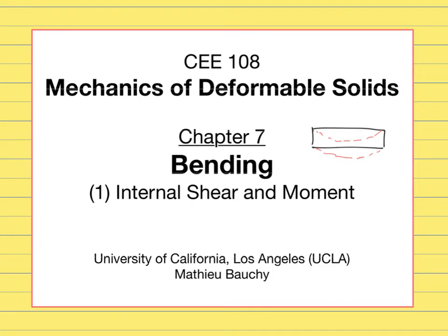So when you think about bending deformation, there are really two ways that you can induce a bending deformation in a beam. The first way is to apply a transverse load. So if you have a beam like this, and for example, you apply a 3-point bending like this, so you have two shear loads like this, and then one shear load like this.